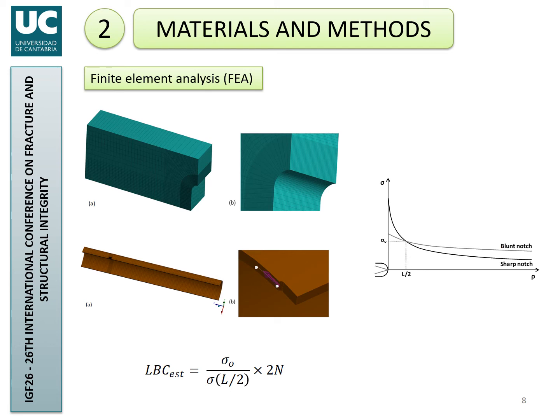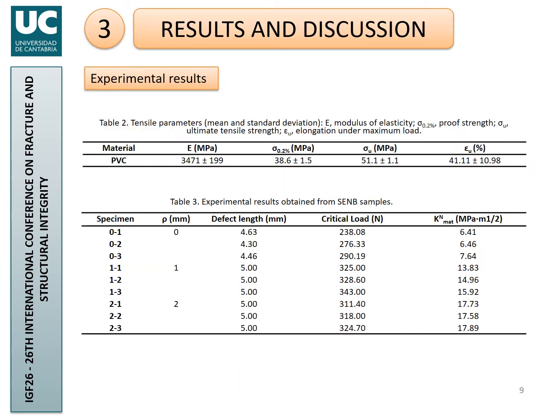When we know these parameters, we simulated the tubes as well, and we introduce the external load till at the notch tip we reached the critical conditions. The simulation in the tubes was made for a unit load, and then finally we obtained the load bearing capacity estimation by scaling this simulation.